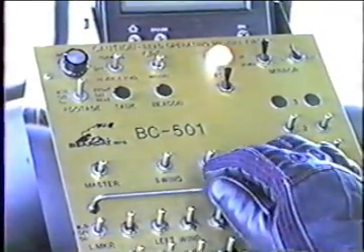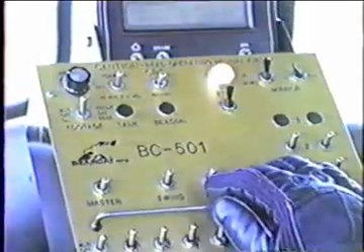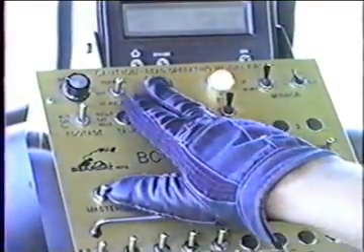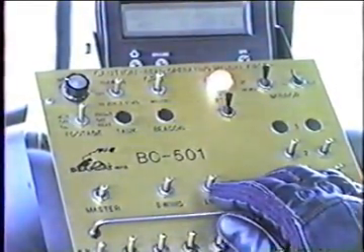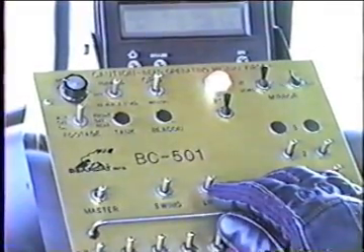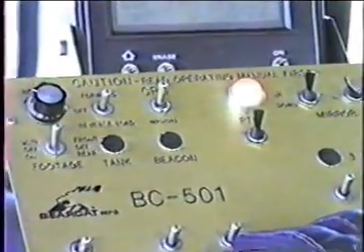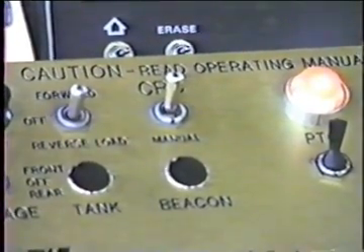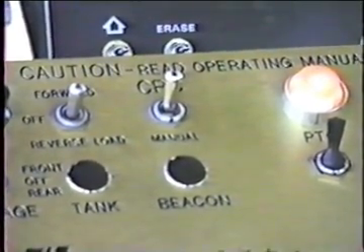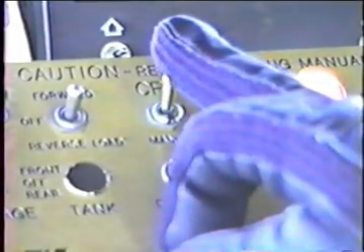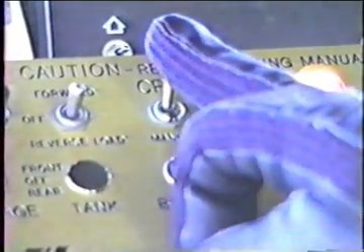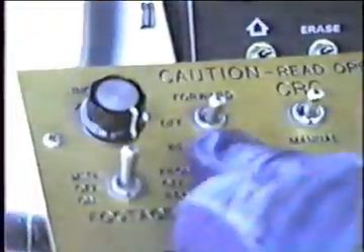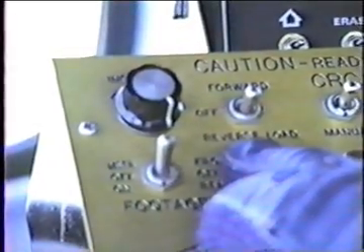Recall when we were at the back of the truck, we talked about loading the truck. 95% of the time on the computer truck, you're going to have the CRC switch in the CRC position. The computer is managing the pump. When it comes time to load it, come to the cab, put the CRC switch into the manual position, put it into reverse, and put it at full speed. And we call that reverse load on the panel.